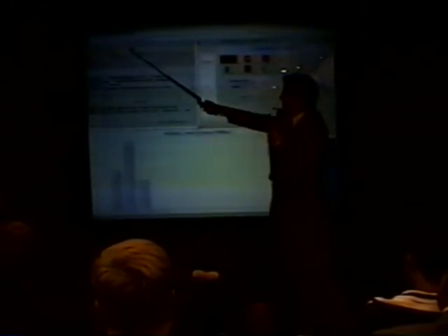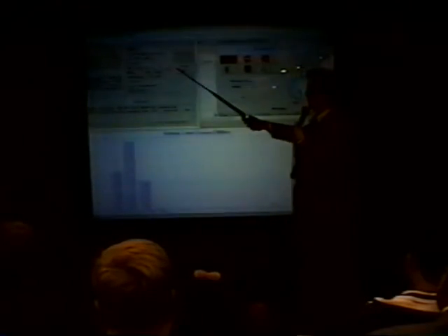Once we've completed our design and we're ready to move forward into the synthesis environment, the Visual HDL product gives us the capability for generating either a full VHDL or a Verilog description of our design and targeting that description towards a particular synthesis tool. So by selecting a synthesis and identifying the vendor, we can ensure that the code that's coming out of our tool is going to be compatible with the style restrictions placed on you by the synthesis tool. This also guarantees that the code that we've generated will be optimized for that tool to guarantee that we get optimal results at the gate level from the synthesis.